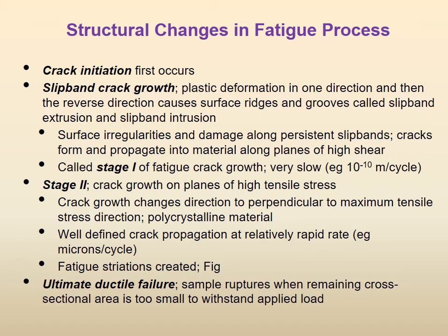Now, structural changes in the fatigue process. Remember, we have talked about failure under impact loading. We have talked about failure under tensile loading, when we keep on increasing the load and how the crack propagates. Now there is fatigue loading. So what changes happen structurally inside the material? Crack initiation first occurs.